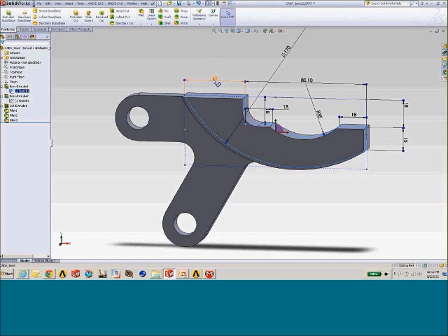One nice thing about SolidWorks is if you roll the mouse over a particular dimension, you can see the dimension name that's assigned to it. So for instance, this horizontal dimension here is D3. That's one that I won't be bringing across. Here's my jaw length. I've renamed it from its default designation to MP_jaw length, again, to filter out all parameters with an MP and to have a name that I'll recognize.